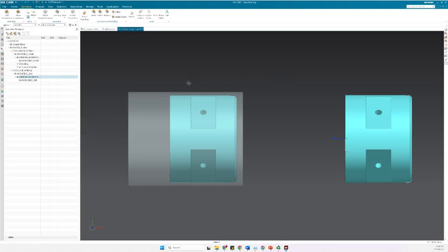What we need to do next is to define the containment plane and also the avoidance. Where does the tool start for both of these spindles, and also where is the position of the spindle chuck, so that we avoid any collisions. So again, we go to the main spindle. We double click on the avoidance main.